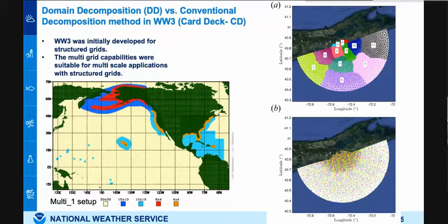So the problem arises when we wanted to go to higher resolution, which means that we need to have a larger grid, and then we need to use more CPUs, but the wave model had some limitations. So all of them led to some slowdown in the model, which was not appropriate for our purpose. So for this reason, we implemented a new parallelization algorithm as shown in the upper right panel. This algorithm is based on parametric libraries, which is well proven in other models like ADCIRC and FVCOM, and we also introduced an implicit numerical solver to avoid the CFL constraint in the explicit scheme.